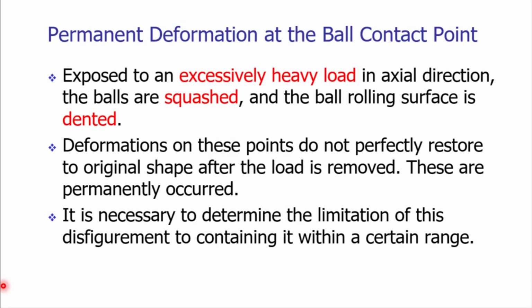Due to very high loads in the axial direction, many times the balls are squashed and the ball rolling surface is dented. So there is deformation on these points, which do not perfectly restore their original shape after the load is removed; these are permanent. So these dents are nothing but the deformation on these points which do not restore their original shape.